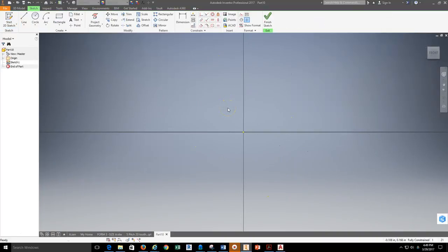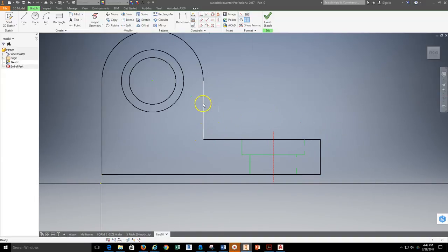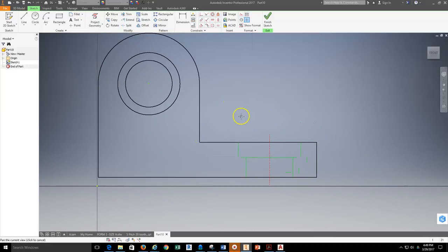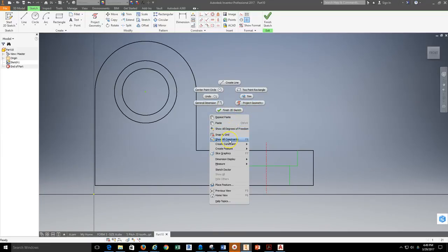From this point, I'm just going to do a Control-V, and that's going to bring in the geometry that I copied from that AutoCAD file, and I'm going to paste that into my sketch by clicking with my left mouse button. And it's now going to go through the regeneration process to make this geometry visible. It takes a little bit of time. I'll zoom out, and I can now see this is line geometry that has been placed into my Inventor file.